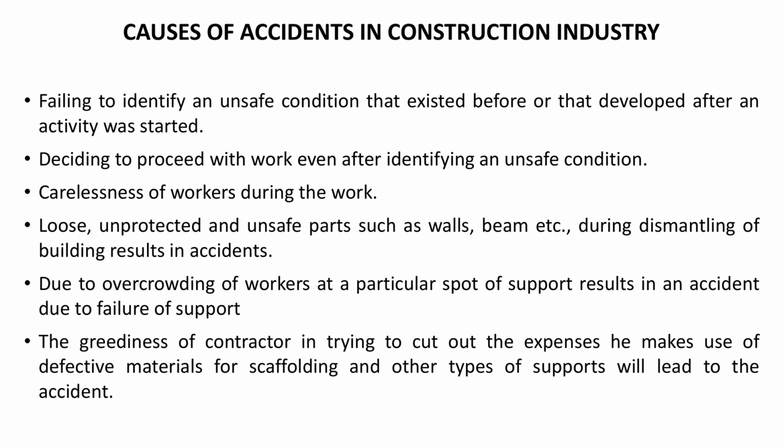Overcrowding of workers at a particular spot of support results in an accident due to failure of support. The greediness of a contractor in trying to cut expenses makes him use defective materials for scaffolding and other types of supports, which leads to accidents.